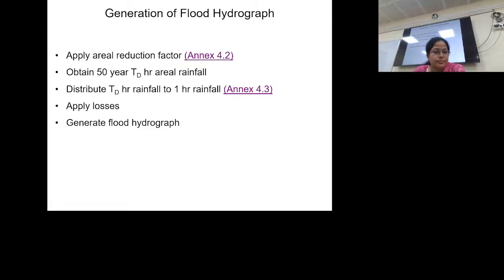They have analyzed some catchments. When they say it's a homogeneous catchment, they have analyzed some hundreds of catchments in that main catchment, and based on that they have found the equivalence. So what is the equivalence? That is how to convert that point rainfall. They have given some tables. So you use those coefficients based on their analysis, and that coefficient they have given in Table 1. We use that coefficient and convert our point rainfall to the areal.